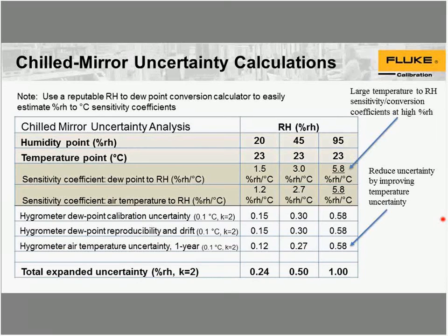Another question about the RHapid-Cal is what is the accuracy of the temperature and humidity probe. The humidity accuracy is 1% RH, and the temperature sensor is 0.2 degrees C. A question about comparing humidity results to the two pressure and mixed flow unit. We'll get some more information for that and see how to put that into this. I see that's a common question, so it comes up twice here.